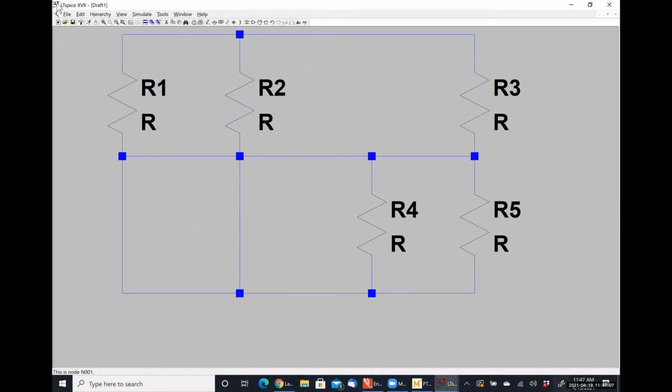And I know that my phase angle is negative because I have shifted this thing in time to the right by some amount delta t, right? So I know that delta t is measured in seconds. My frequency is measured in radians per second.